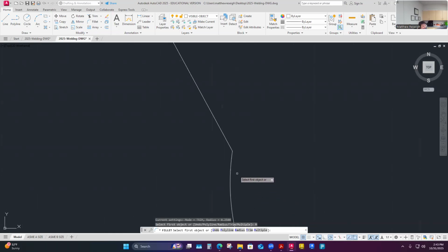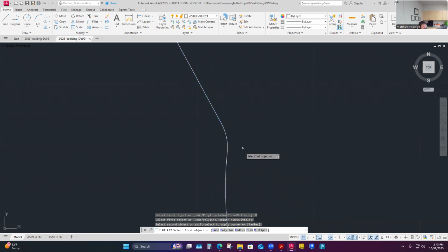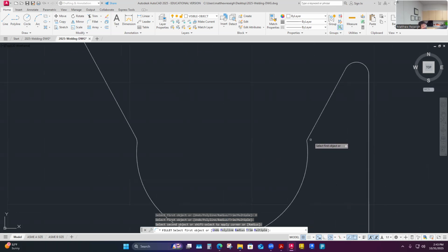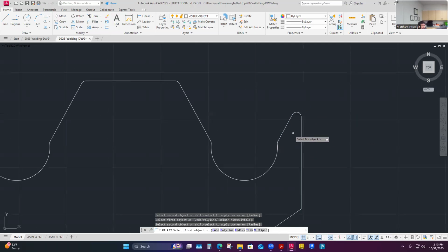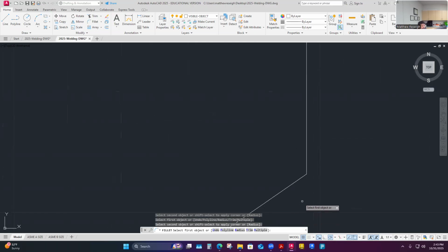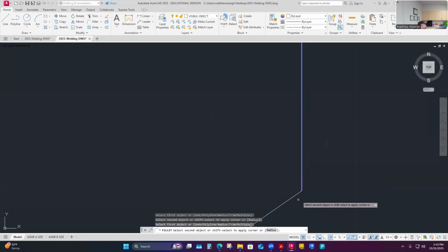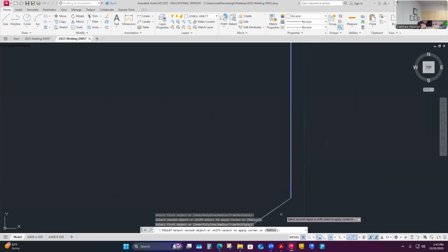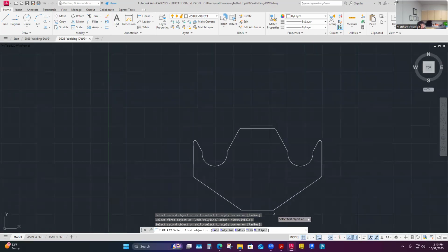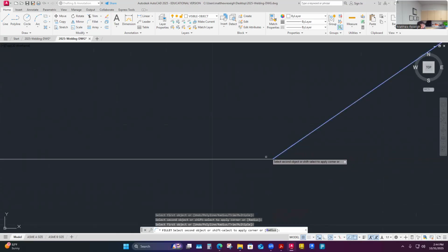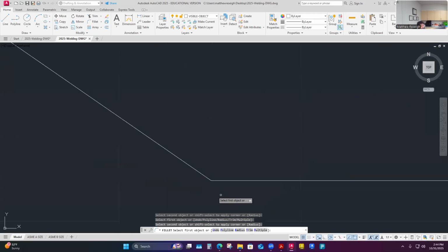And this is an additional annoying thing about the fillet command. You get used to it in CAD if you use it a lot, but now my command just stays continuous. So now I can go along, applying the same quarter inch radius to all the corners. I've set the radius at quarter inch, and I've also set it up to be multiple selections. And so now I can finally start going to town and doing all the quarter inch radiuses.